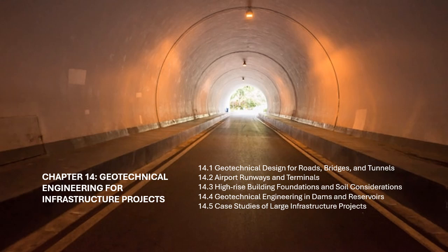Groundwater control. Groundwater levels can fluctuate, especially in areas near water bodies, affecting the stability of terminal foundations. Geotechnical engineers assess the risk of uplift forces due to high groundwater pressure and implement dewatering systems, such as pumping wells or wellpoint systems, to control the groundwater and ensure a stable foundation environment.